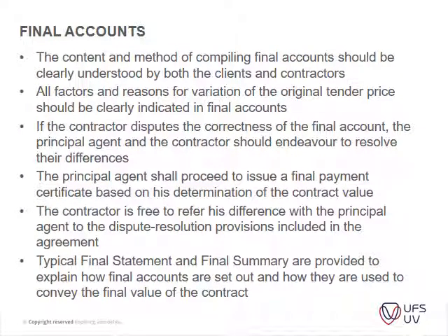Then the content and method of compiling final accounts should be clearly understood by both clients. So communication is key here. That's why it's important to keep the final account up to date during the course of the project. All factors and reasons for variations on the original tender price should be clearly indicated on the final accounts. So it's just record keeping of any changes.